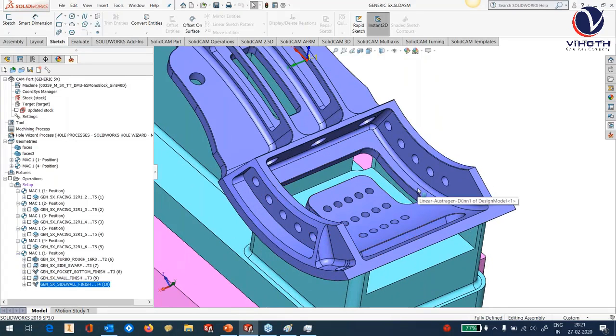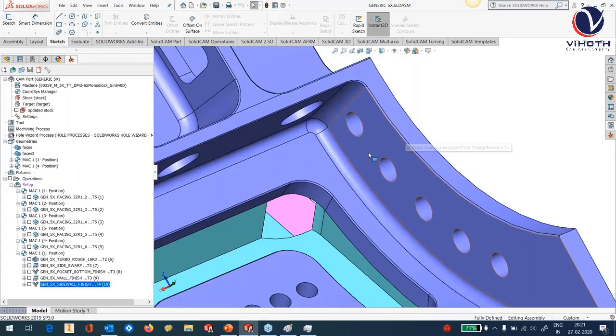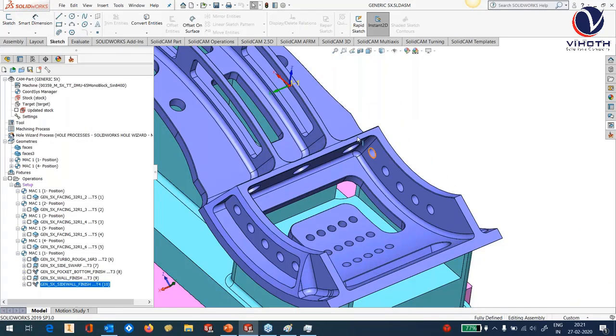Right. Now let's come to the main area that we need to be careful about. Although some of our technologies today can handle holes and other things as part of the links, a better way is always to close them when you're doing 5-axis, especially when you're using the circle end mills or our barrel tools. Okay, because now I'm going to use barrel tools to machine the inside of this region, the walls.